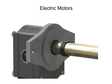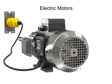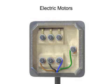If the motor's rotation is incorrect for the required application, it can be reversed by simply interchanging the connections to any two of the three power wires.